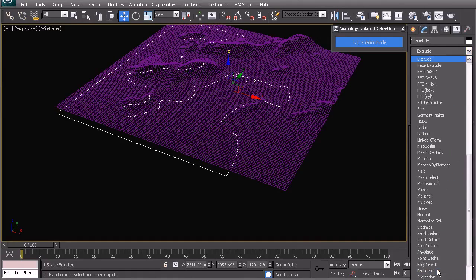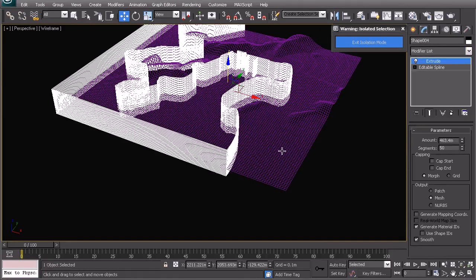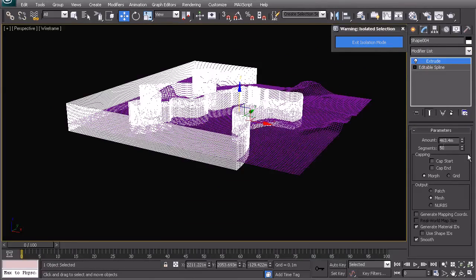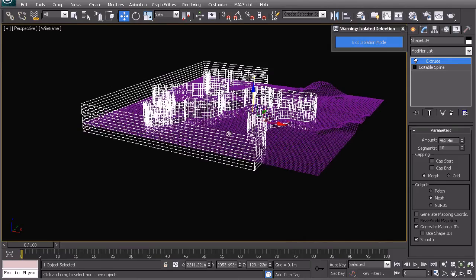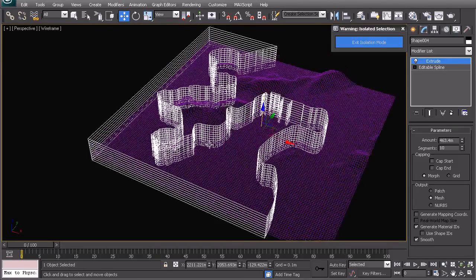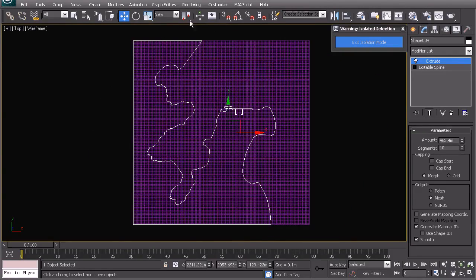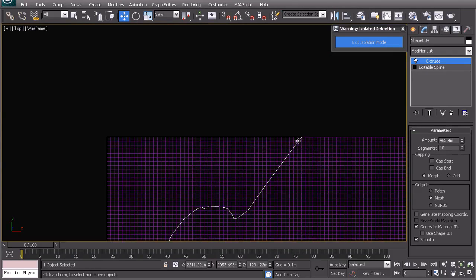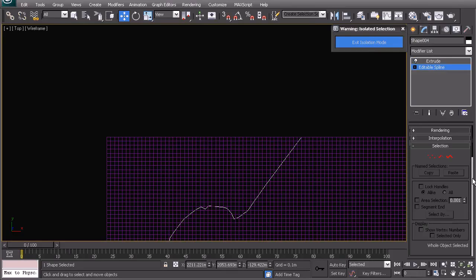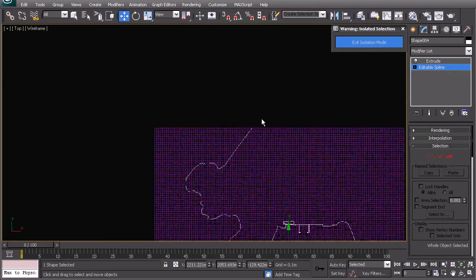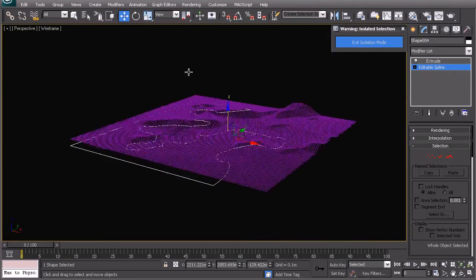We're going to extrude that. And as I've extruded it, I've just left a couple of segments in it. We don't need 50, we can use slightly less. Sometimes you really don't need to do it, but it does help. Maybe 10 is good enough. And in our top view, we can just check that it's out. Generally it helps if this part is actually outside. I just don't want to make it less accurate by shifting too many things around. So let's just give it a go like it is and see if it works.